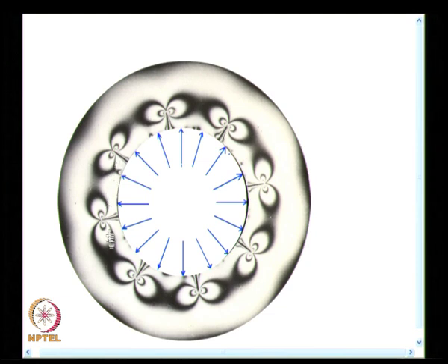It was done by my student DPS Chauhan way back, and you find the fringes are very nicely formed, and you also find that there is no major interaction between the cracks here. So, this is another conceptual understanding that multiple cracks can exist without interaction, unless they remain very close. We would see another example in the next class, where there could be some kind of crack interaction.